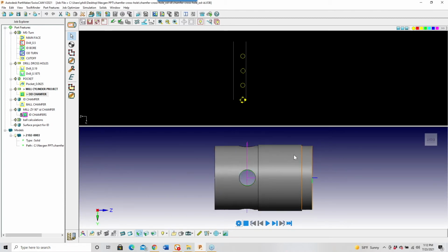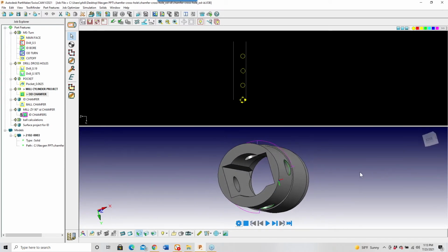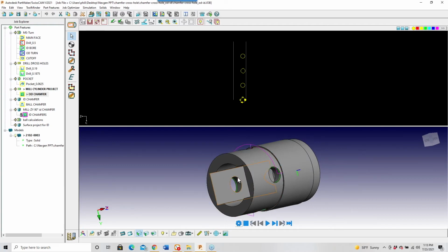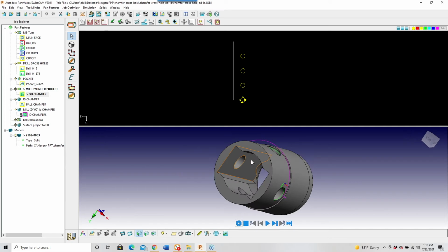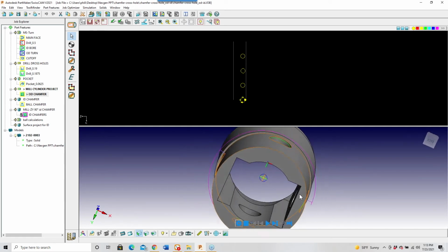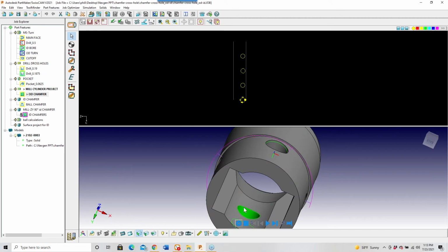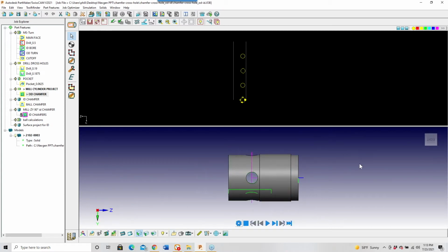They're pretty straightforward. Now the ID chamfers, they become a little bit harder to do. And I've got two samples here. The first sample is for a flat bottom where we can just position the tool and run a 2D tool path, and then a surface project pattern that will create the chamfer on the inner edge here. All right, so let's look at the flat pattern first.